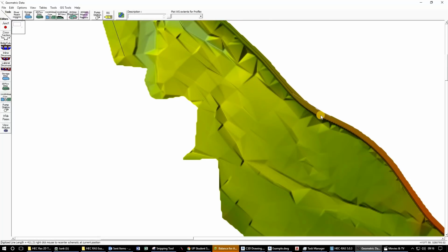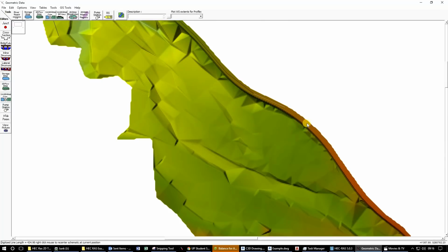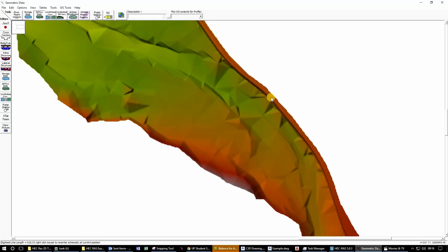If you press and hold shift, and then as you guys can see the cursor change to a little hand, and then if you click and drag, you can drag the map around. That helps with navigating because zooming in and out with HEC-RAS 5 is absolutely horrible. They should honestly work on that. But anyway, let's just trace this and then see what we get in the end.